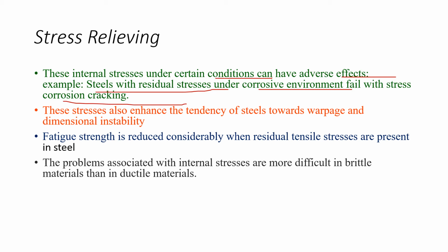The stresses also enhance the tendency of steels towards warpage and dimensional instability. Fatigue strength is reduced considerably when residual tensile stresses are present in the steel. The problems associated with internal stresses are more difficult in brittle materials than in ductile materials.